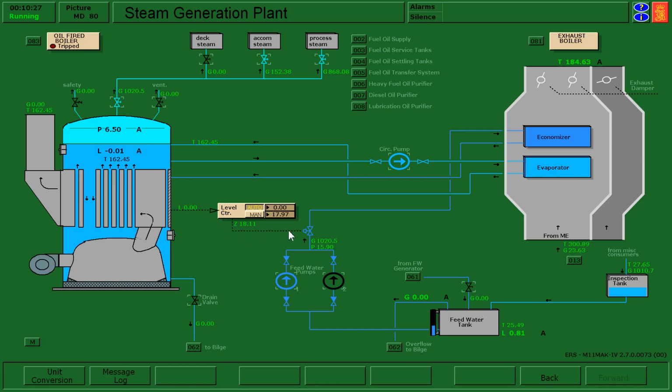have a couple things. Number one, we need some electricity in order to run our control systems. So a higher priority item for us in terms of starting up the boiler is going to be making sure we have electricity. The other thing that's interesting is, how does this valve actually work? Well, we haven't looked at it in class yet, but these control valves are often pneumatic valves, meaning they run off of compressed air.